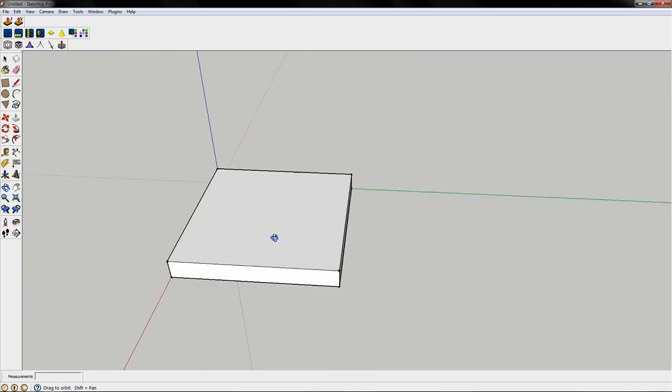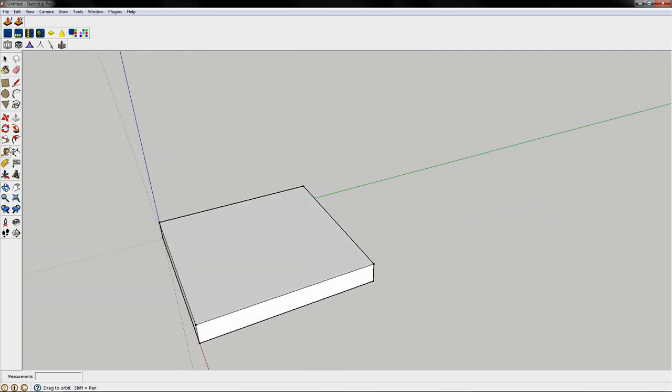Now I'm going to draw a rectangle on here, but to do that I'm going to offset this side. So I get this tool here, the offset, go over this face, it goes dotted again with the red mark on the outside, click, drag in, and then it offsets the whole edge, that whole face edge. I'm going to offset that by 50 millimeters maybe.